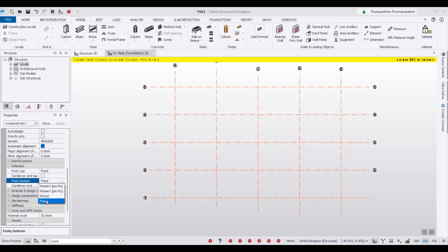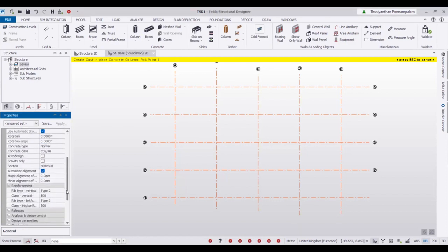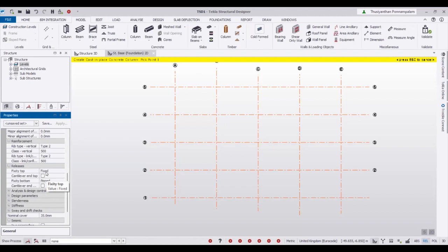Okay, now the column bottom base is a foundation, right? So I am going to use a normal pad footing, let's say. Then generally we pin the connection. We don't transfer the moments generally. It depends on the type of the building. Also, it depends on the framing system, what framing system is used. But I decide it is pin, right? So our foundation design is straightforward. Right, so releases, okay.